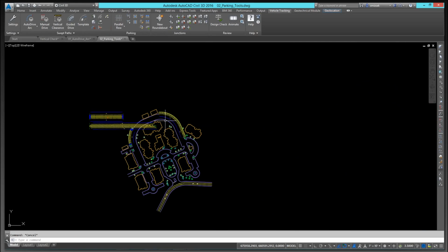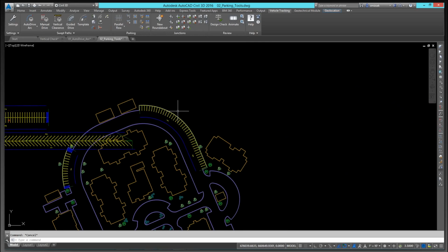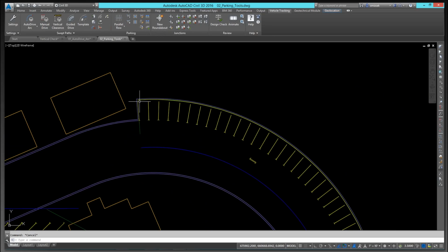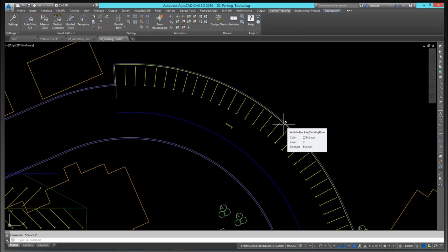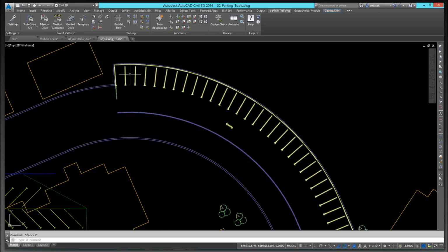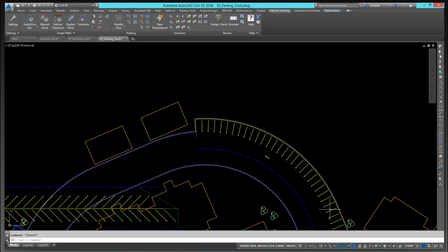I went in, like I mentioned earlier, I went into the parking standards and I actually created a new service and I called it P, and I set my stalls up for parallel parking. Because right now this is 10 foot wide, 18 foot deep. Well, I made a new service that was 22 feet wide, but only 12 feet deep. So I was able to do parallel parking through here. So by doing that with the new service, I was able to create parking stalls for parallel parking.